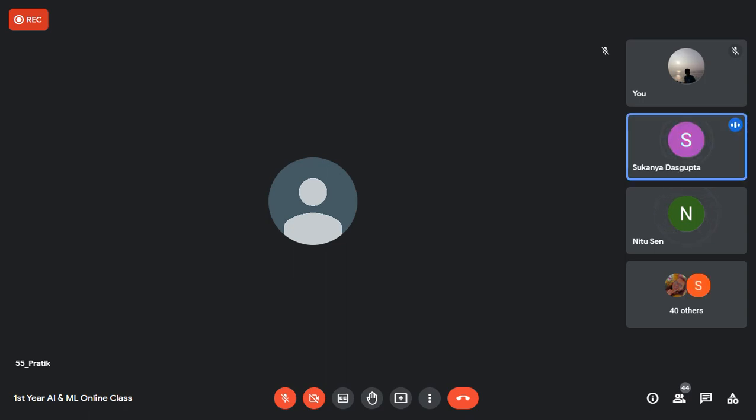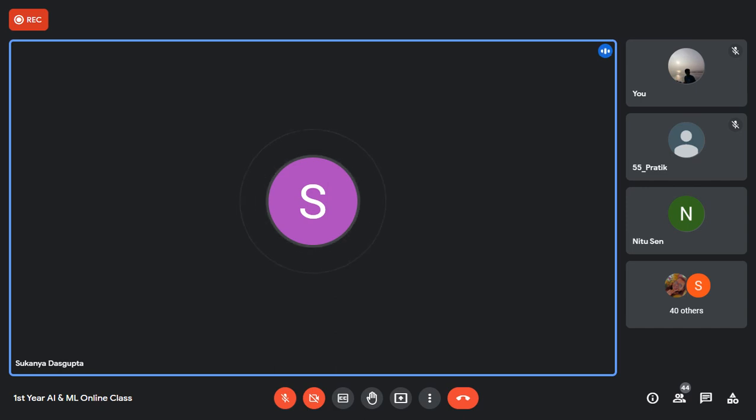Completed. Okay. And one more thing, students, please note that from the observation table, if you draw the speed versus armature current graph, with speed on the y-axis and armature current on the x-axis, you will also get a straight line type characteristic curve, right?